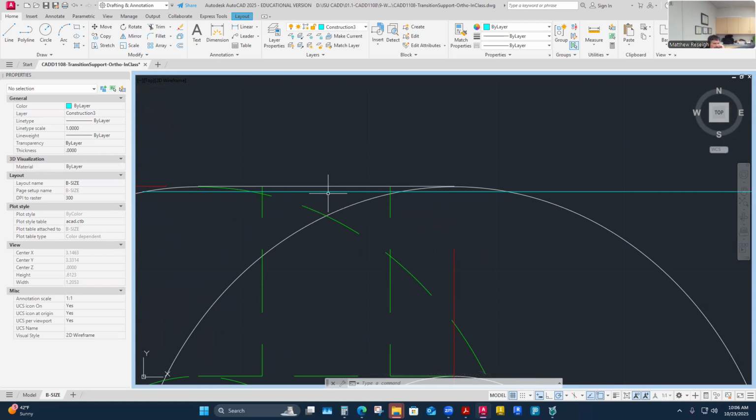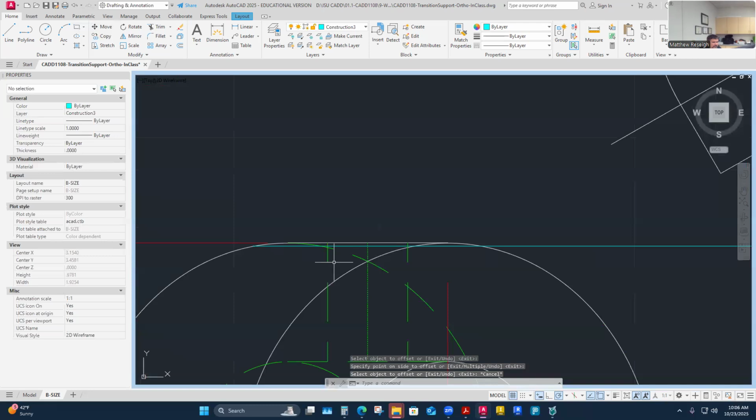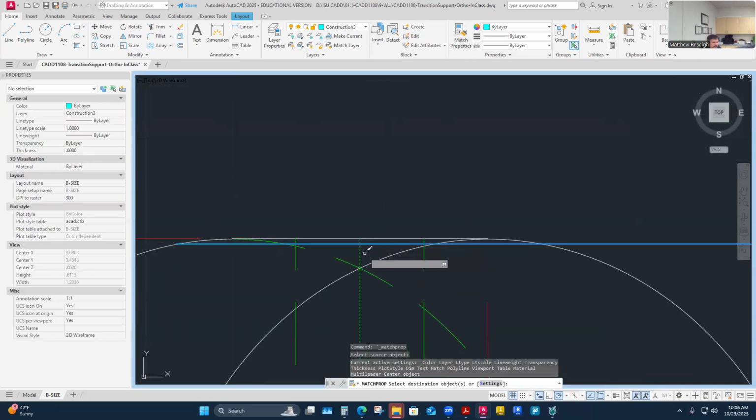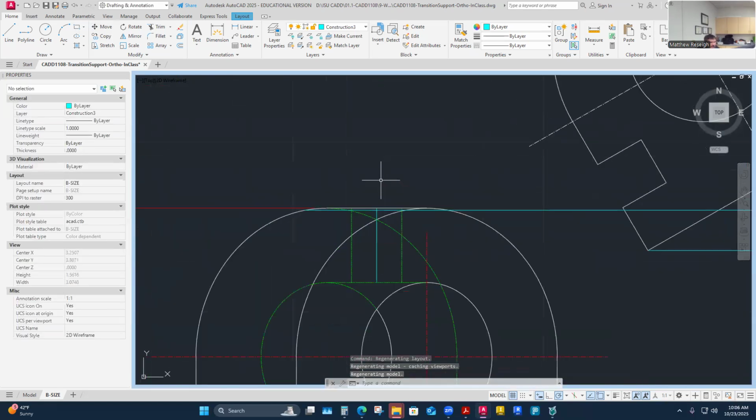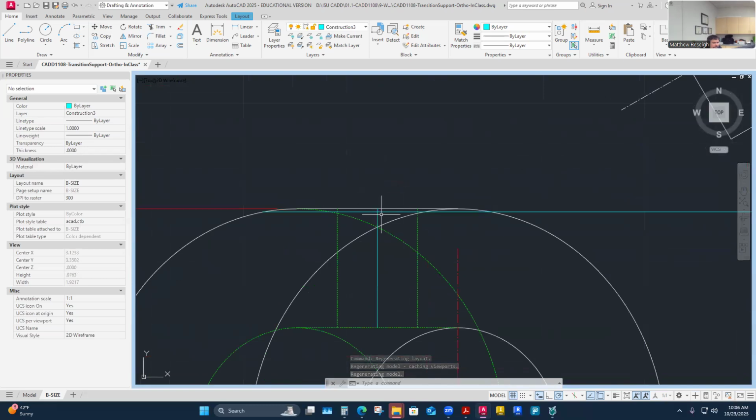I need a center. I need a cross center, the center between those two holes. That's a 1/4 inch diameter. So I could offset this. I'm still on the 1/8 inch offset. This I'm going to move to the construction layer though. This is a construction center line to me. Technically, I need that. Actually, it's something that I haven't added there either, my center line through that hole.